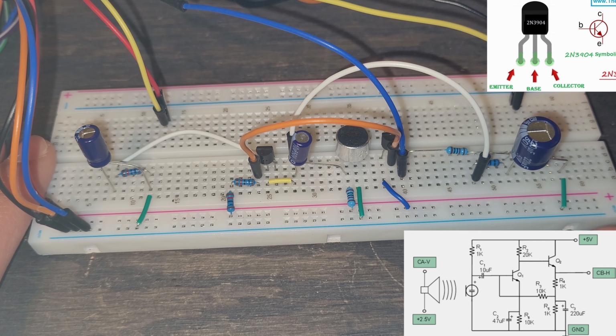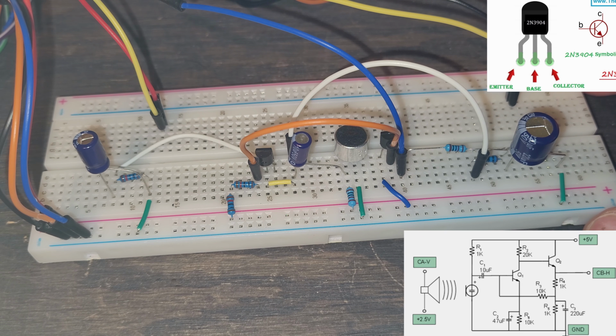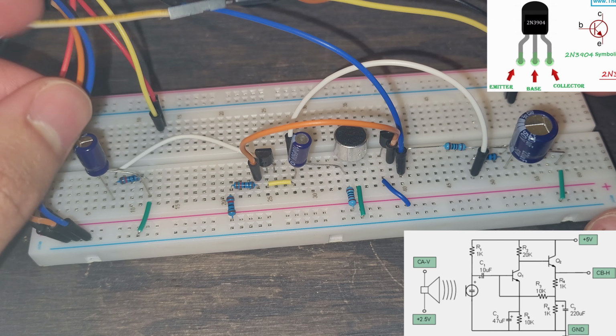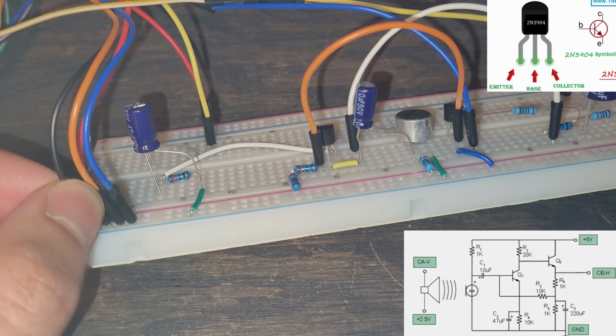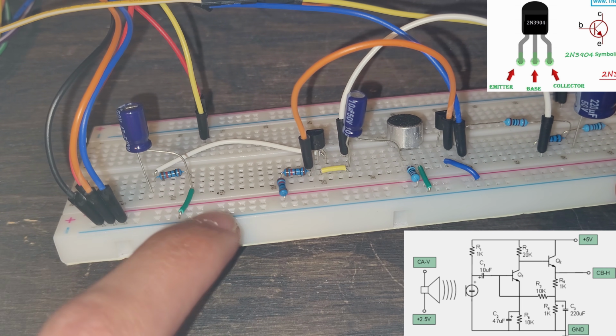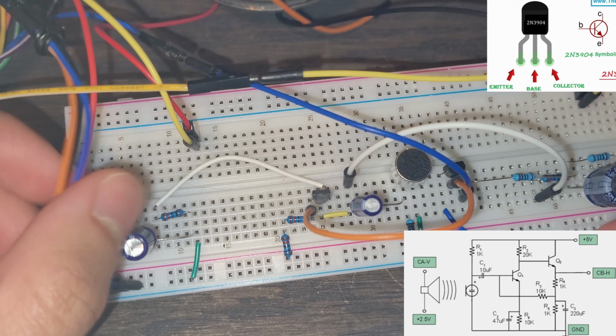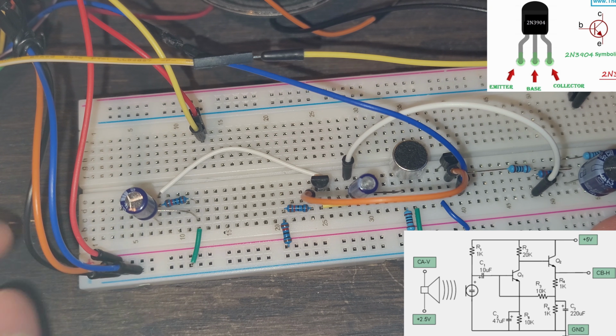So the first part is establishing our 5 volts and ground. In the software, we have our Analog Discovery 2 hooked up. That's what these wires are coming from. And we can see that this black wire is ground. So this black wire is going in here, grounding out this entire negative side. So this negative side is ground, and the 5 volts is going to be this red wire. So the entire red rail is live.